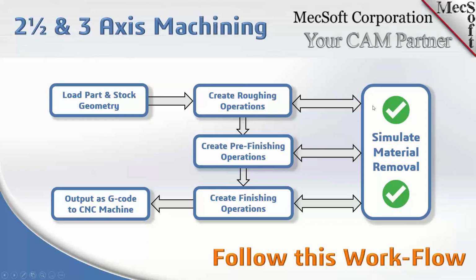Now, if you move to the far right, you see simulate material removal. And you see that arrow goes to the left and the right. So anytime you create a new operation, you want to simulate it so you get an understanding of where that tool is going to go, how it's going to cut. And you want to do that every time you make an edit, but also every time you add another operation, because for instance, a second operation will be based on the cut material simulation of the first. So you need to do a complete simulation of all of your operations to get a clear understanding.